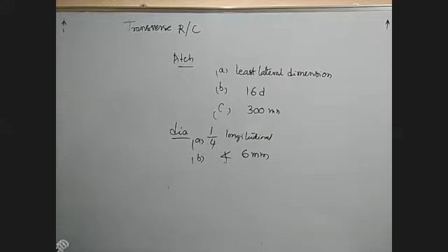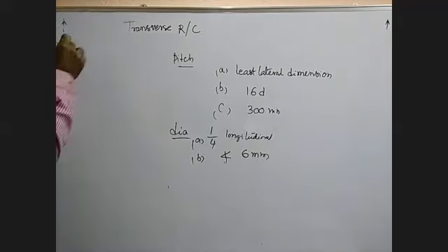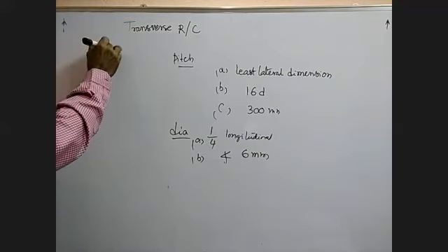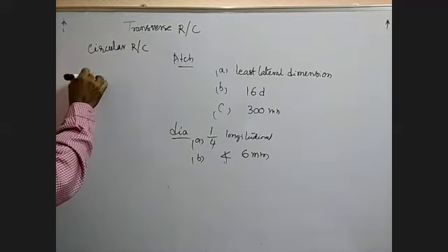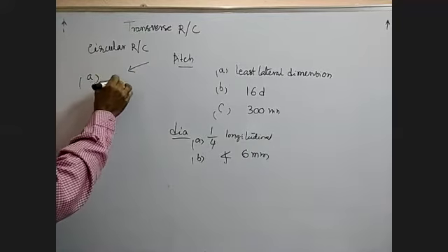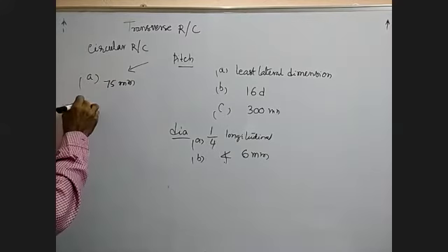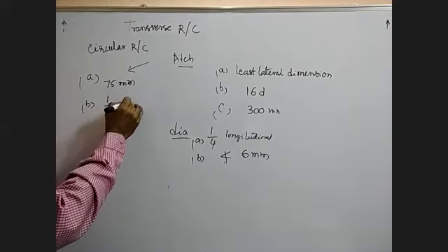అదే helical reinforcement, circular reinforcement అనుకోండి. Circular అయితే this is regarding the lateral ties. Now coming to the circular reinforcement. So the pitch should be, circular అయితే ఎంత ఉండాలంటే 75 mm. This is 1/6 of the core of the column.